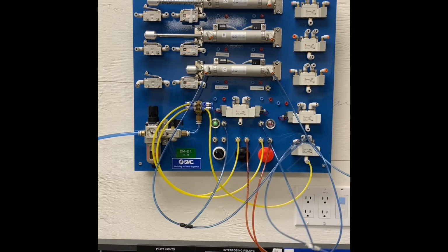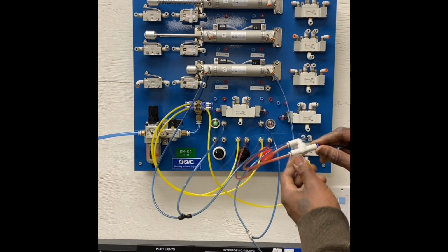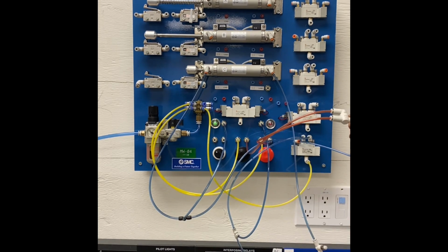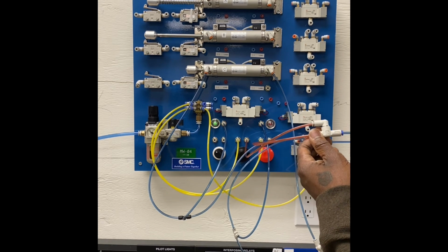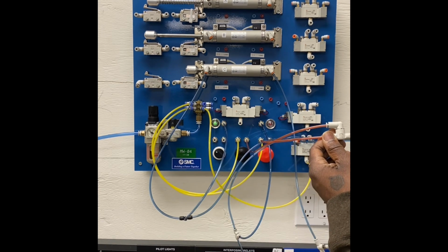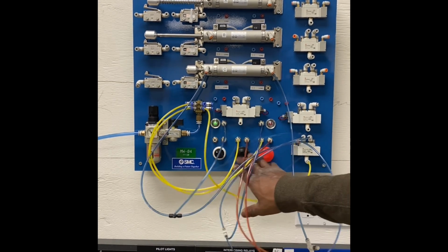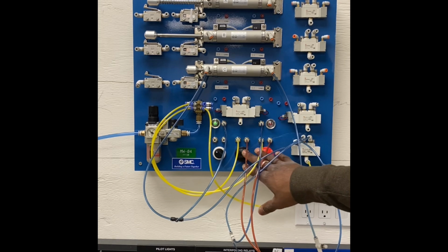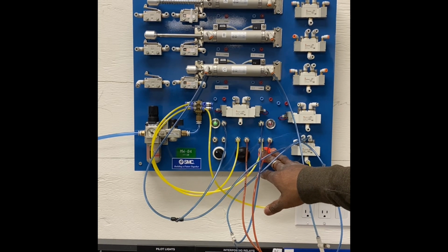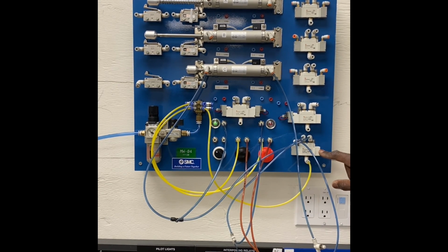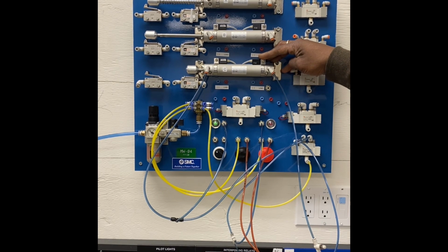Okay? This shuttle valve here is being employed so that when either input is sensed, we get an output. That's the inputs being the push button. All right, so overall here we're using 2 directional control valves, 5-2 pilot spring return directional control valve to control a double acting cylinder.